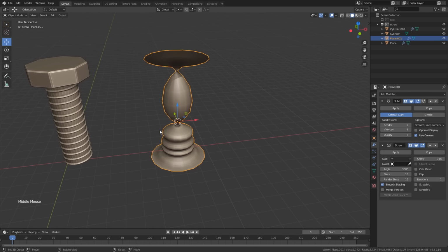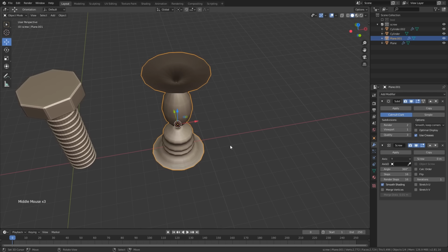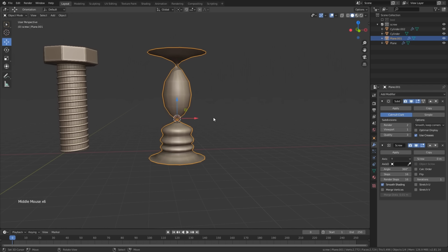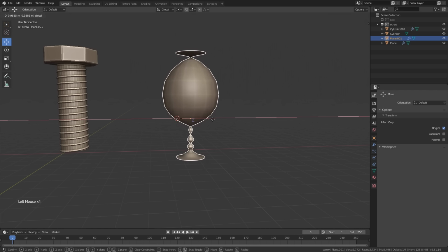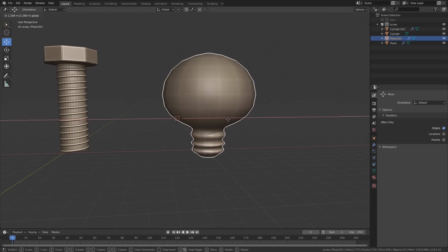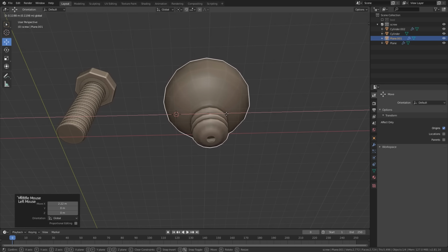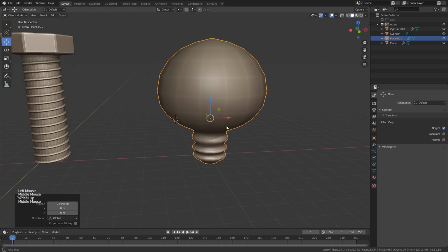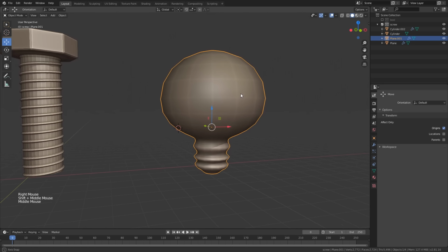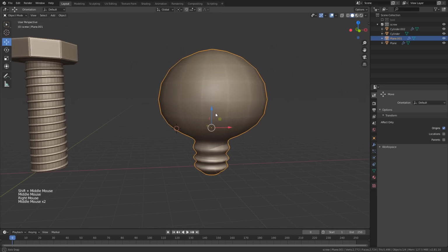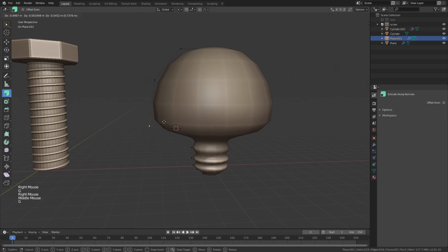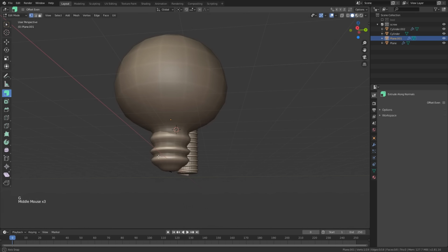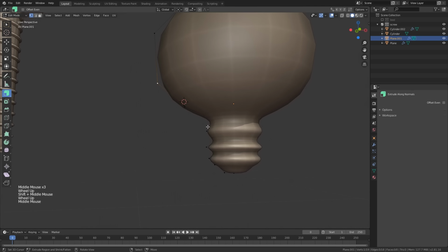Now you can see it's taking the entire shape and rotating this in 360 degrees. Now if I change the origin of this object, let's go to the active tool properties and change this to center of the screw modifier. Now you can see, as I was planning to make one bulb object, I have a bulb. When I change the shape of all these points, this screw modifier is updating everything in 360.